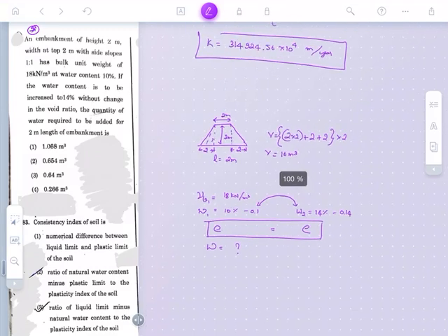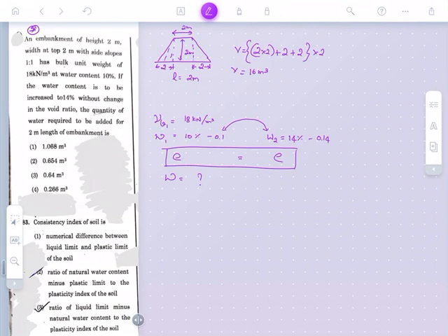Okay, this is the first thing. Next, what I need to find is weight, which will be equal to total weight divided by 1 plus water content W1. This water content W1 is in the first condition, and the total weight in terms of the second condition, when the water content is increased, is divided by 1 plus W2.